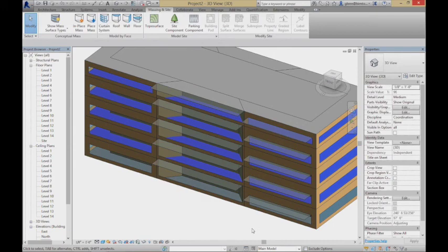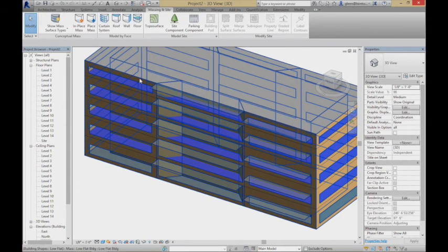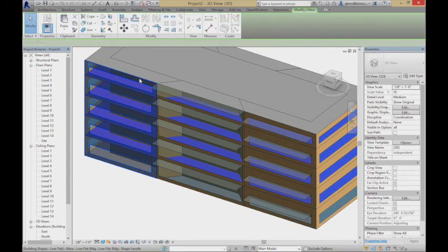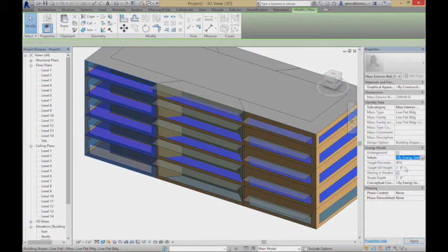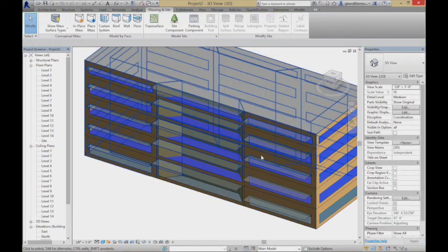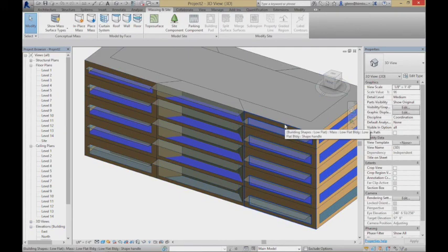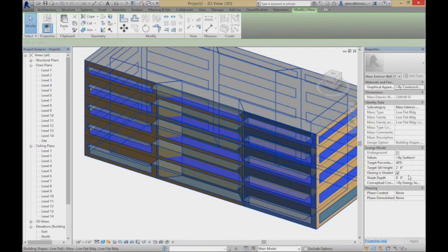Actually, shade depth should definitely be related to how tall the window is, because it's all about providing shading so the sun's not coming in at the worst heating time. Maybe I'll leave that 40. It'd probably make more sense to do smaller shades on the sides, bigger shades in the middle when I put all that glass in.